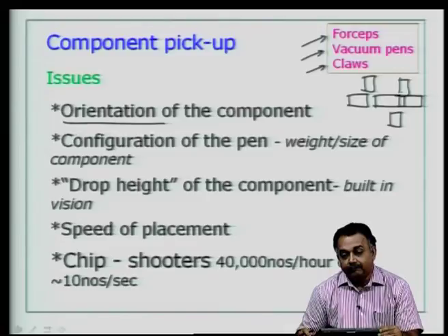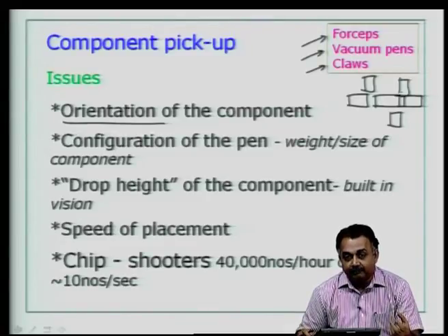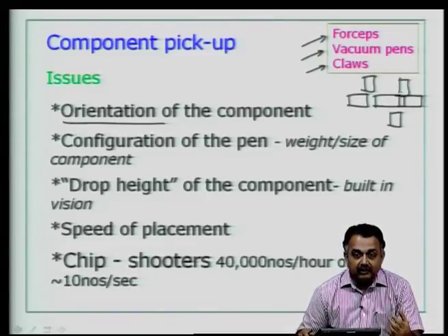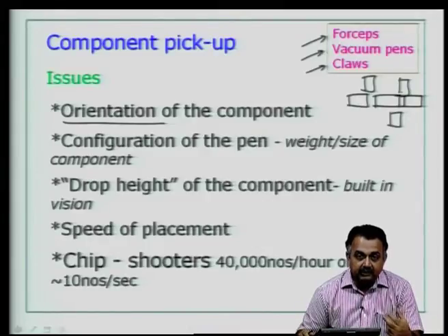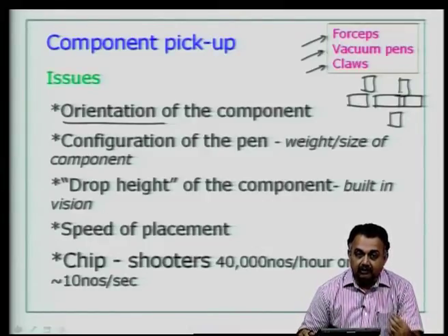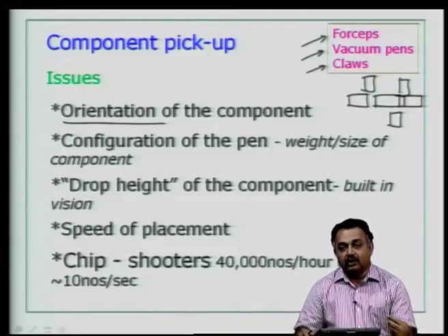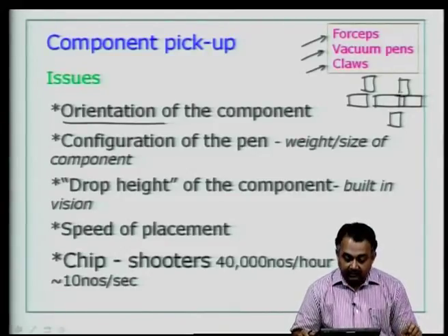So, typically you can view this in high end equipments using a built in vision, whether the placement is perfect and the drop height is well maintained. So, technicians would know how to maintain this drop height in equipments.